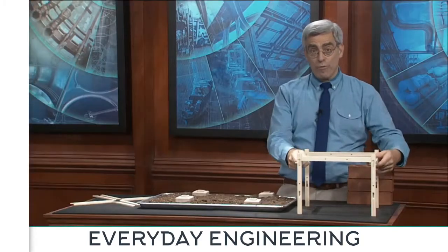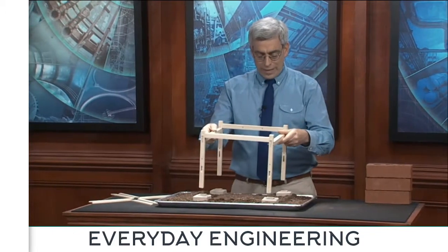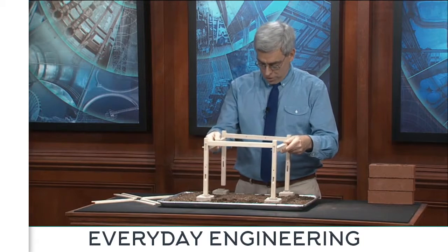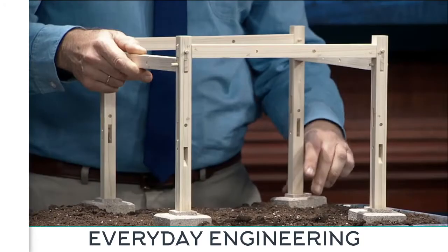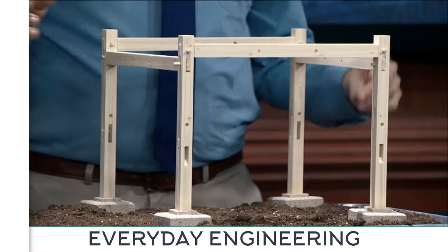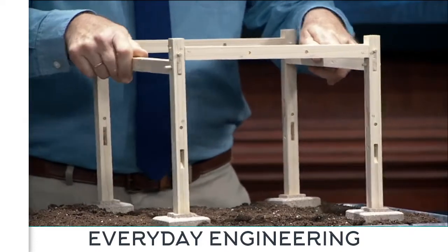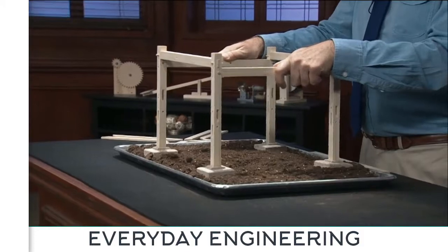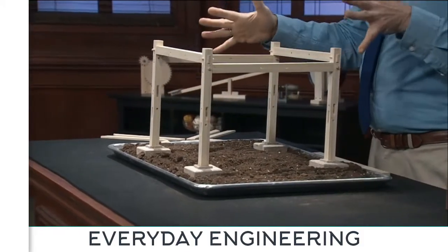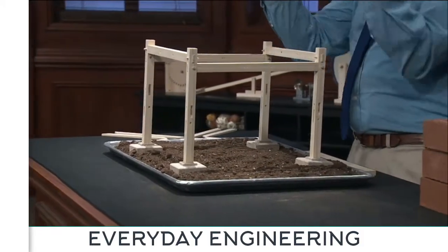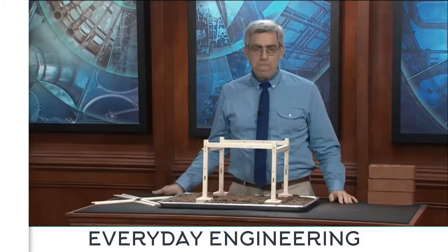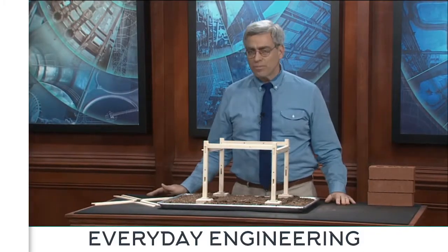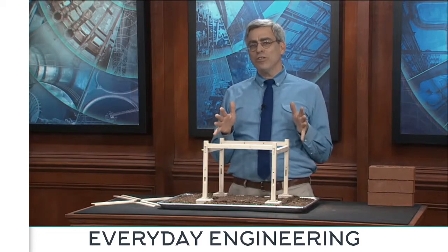Now I'm going to take my wooden frame and place it on a set of column footings, which constitute the foundation for this kind of a structural system. And when I do so, you might notice that the structure is kind of wobbly. It doesn't really stand up straight. So presumably when I put a heavy load on it, it's going to have some lateral instability problems. How can we make this structural system more laterally stable? Well, the answer to that question